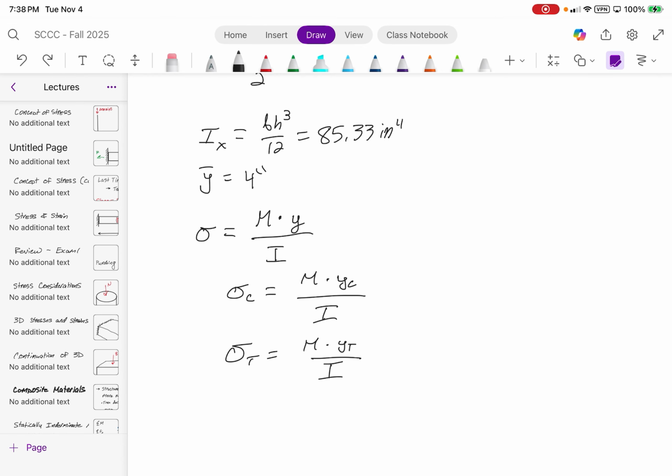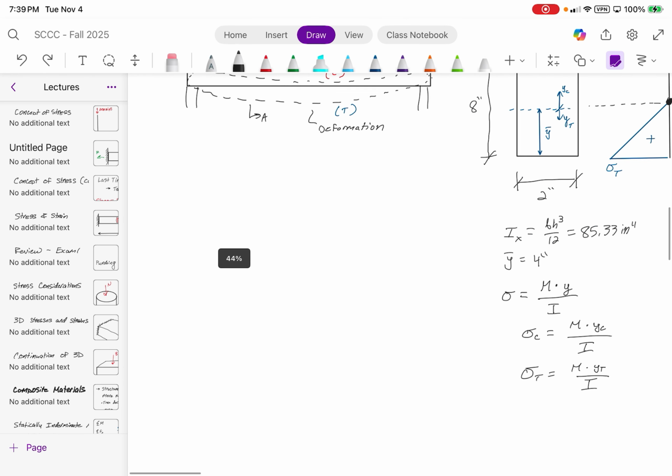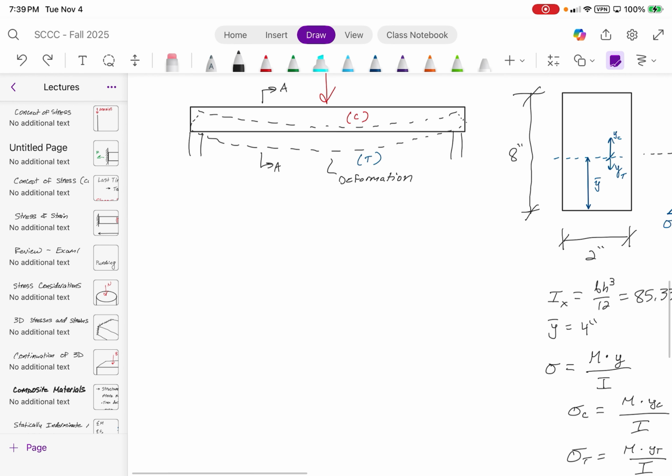Will we have to be able to tell if it's Ix or Iy? Yes. One of the ways that's pretty easy to tell is with W shapes. So if I had given you guys a beam and it was loaded like this, and you were to look at it from a cross-section view, you would see that the load is either going to look like option 1 or option 2 for a W shape. In this case, you would use Iy, and then in this case, you would use Ix. Does that make sense?